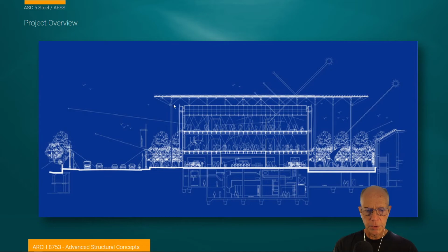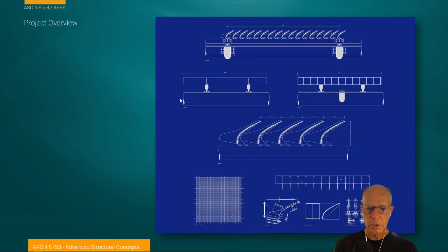This gives you an idea of the arrangement of the full structure from the front elevation with only one column, while in the rear there are multiple columns. If you look, it looks like these columns terminate here. They may not actually go down through the building. They may just sit on structural steel beams of the building itself, and the building itself is doing a really important function, and that is stabilizing this whole structure. The building itself has to act as the shear wall in order to stabilize and support that gridded system.